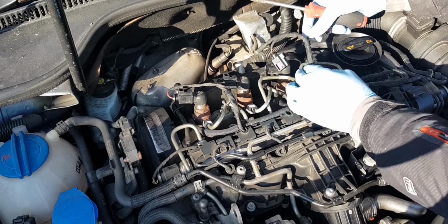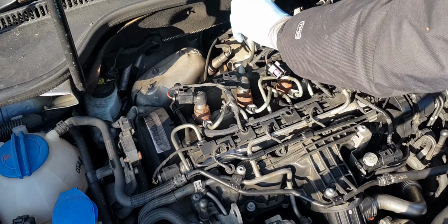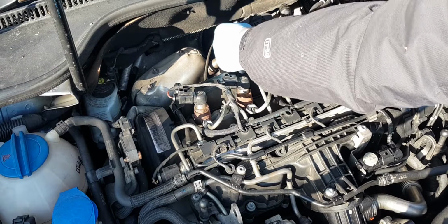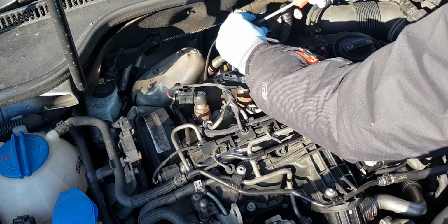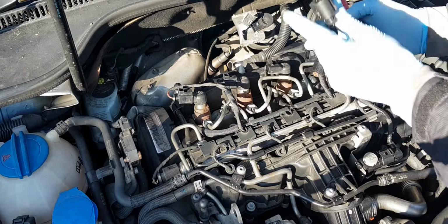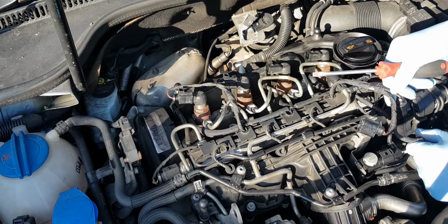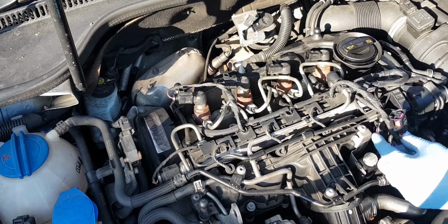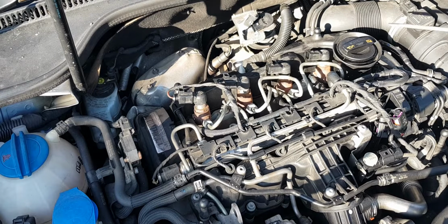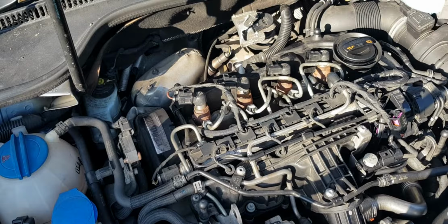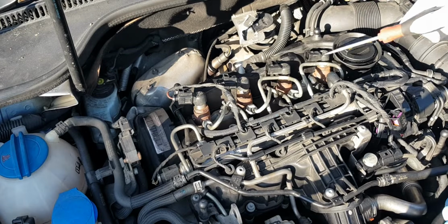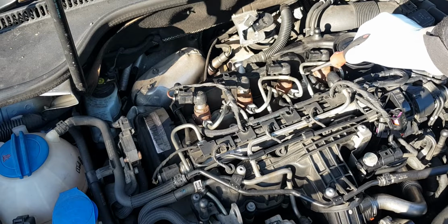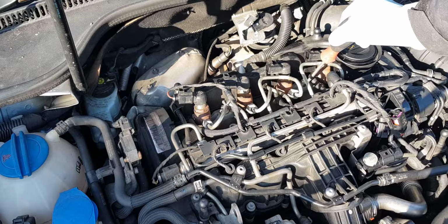And then you just unclip this from the high pressure hose, just to save yourself the hassle. Disconnect the turbo actuator plug as well in the same way and move this safely out of the way. I'm just going to clip it here so it doesn't come back. And what I'm going to do here, I'm not going to obviously touch 1 and 2. There's nothing that I need to do there, but on this side here, number 3 and 4 are held in place by this metal bracket.